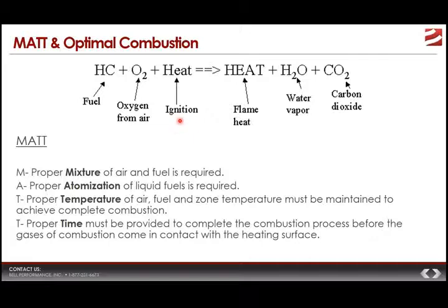And then, of course, proper time must be provided to complete the combustion processes before the gases of combustion come in contact with the heating surface, because once those gases of combustion come in contact, then they will not combust as properly as they should. So if you have all these four elements, you're going to be a lot closer to having optimal combustion than if you didn't have them.